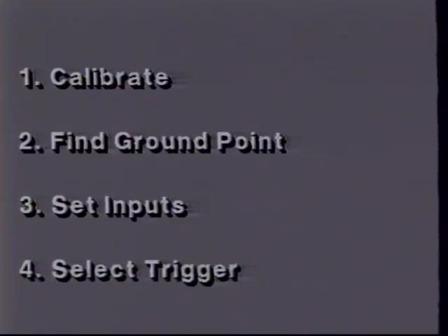We have now covered all the steps necessary to observe simple signals. First, calibrate your probes and find a proper ground connection for the scope. Then set up your coupling, vertical attenuation, and time base. Connect your probe and select Auto Trigger mode. Once you have confirmed that the signal is present, select the trigger slope and adjust the level for the clearest display.